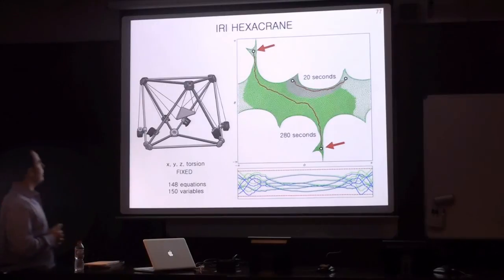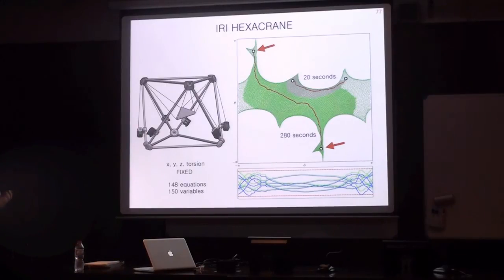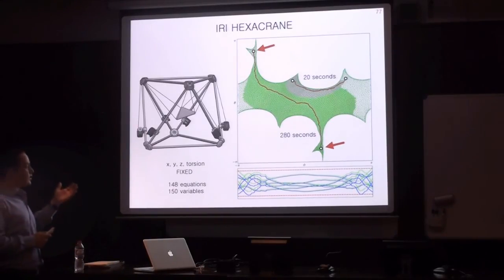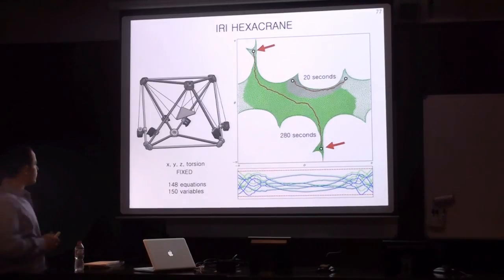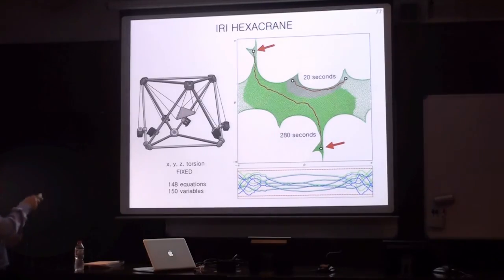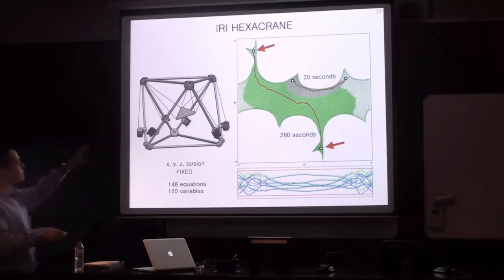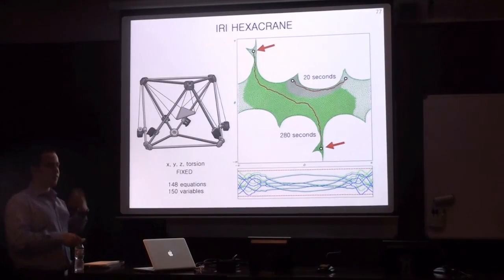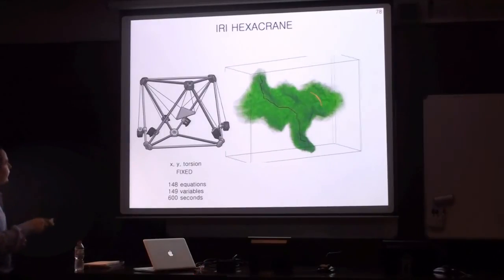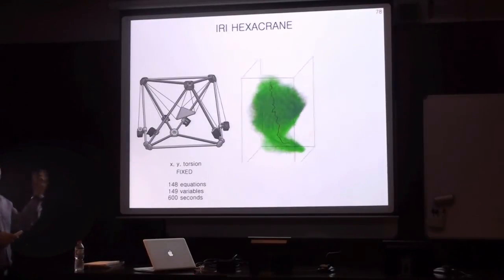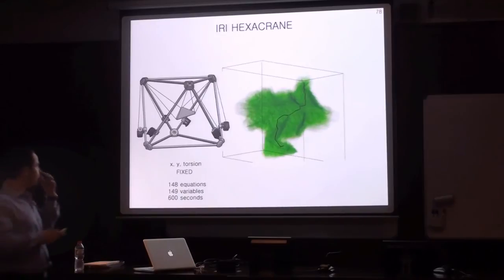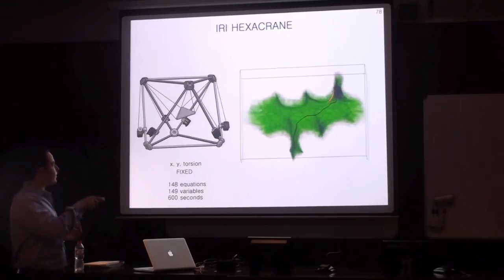To show an example of path planning, in this case in 3 dimensions, we can allow the platform to also move in its vertical axis. So in this case, the charts will no longer be polygons, but polyhedra. And we can see here in green these polyhedra, which are the atlas that was explored to obtain this range-feasible path that can be seen inside.